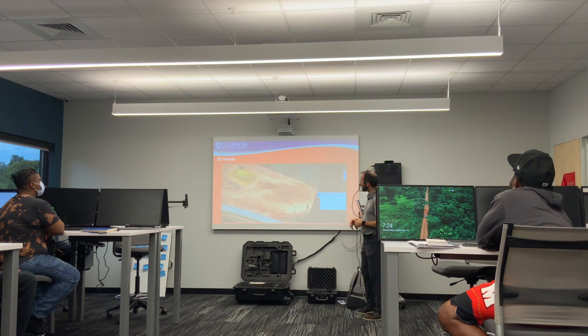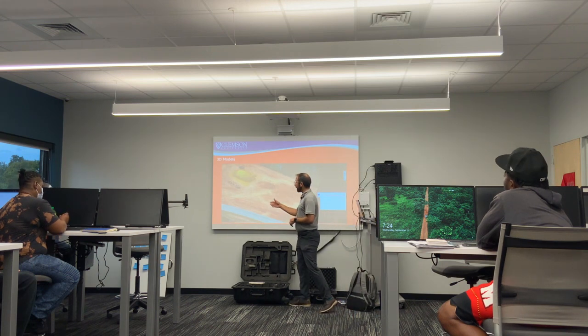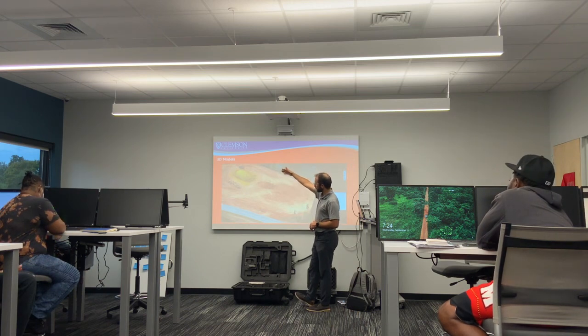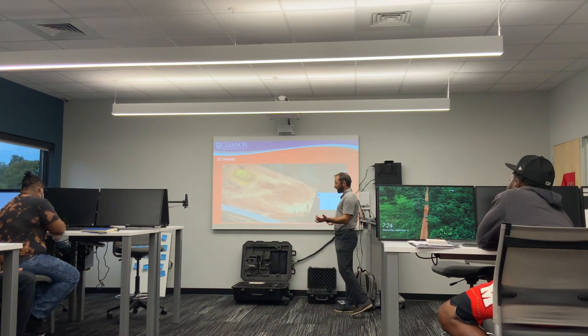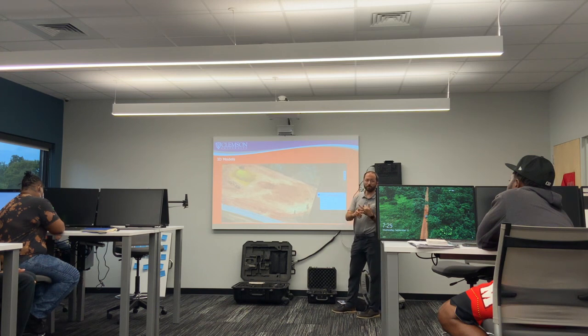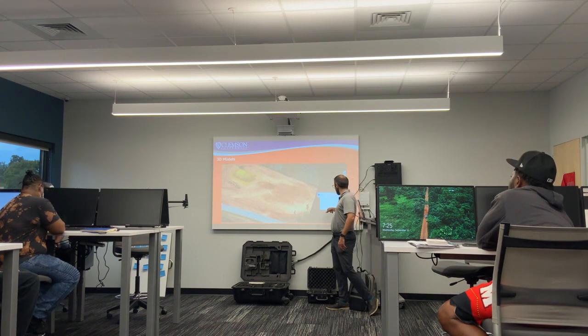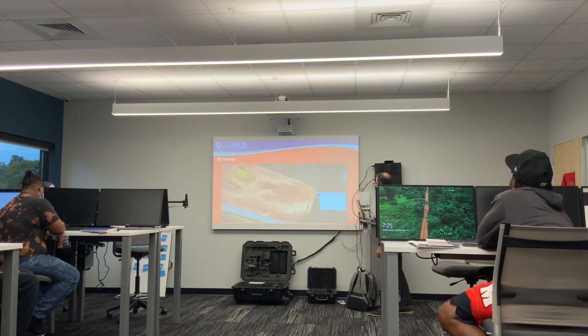This example right here is for stockpiles, which is a big deal. If you're a site work guy, you want to figure out essentially how much dirt is there. That's going to affect how long it's going to take to get out, and what size trucks you need, things like that. So you can see down there the perimeter, and the area with the cut and fill volume: there's 2,000 cubic meters of dirt in that pile. Very important things to know.